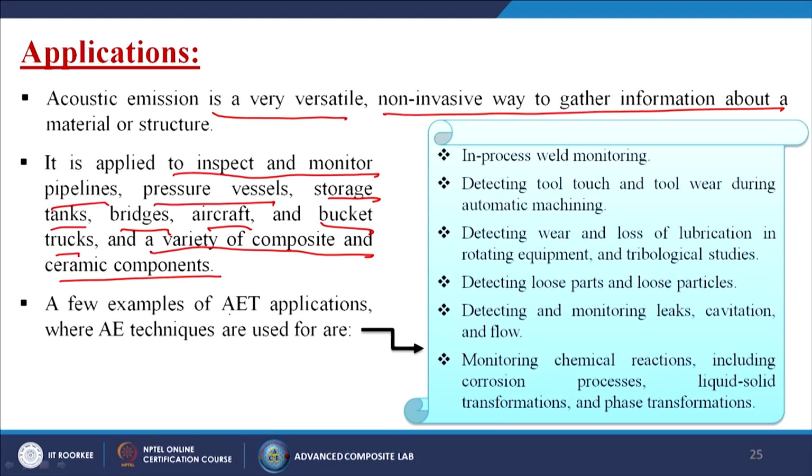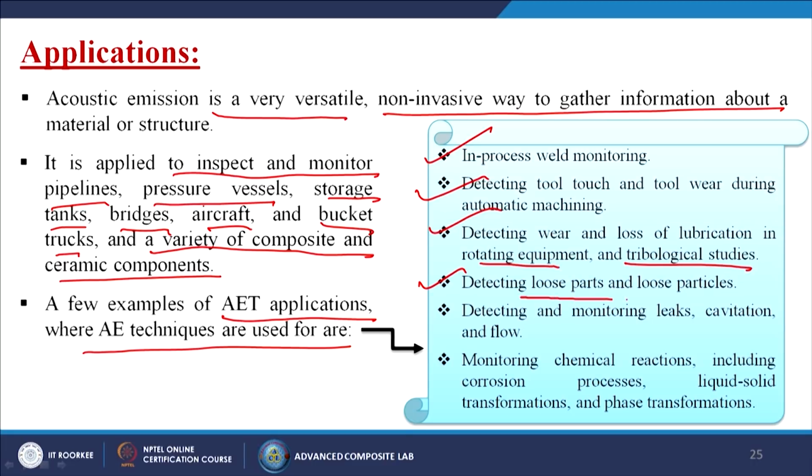A few examples of AET applications are process weld monitoring, detecting tool touch and tool wear during automatic machining, detecting wear and loss of lubrication in rotating equipment and tribological studies, detecting loose parts and loose particles, detecting and monitoring leaks, cavitation and flow, monitoring chemical reactions including corrosion processes, liquid solid transformations and phase transformations.